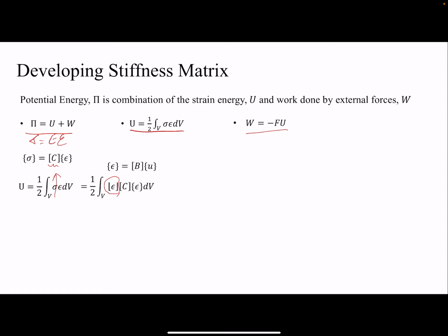So epsilon, I can simplify that. I found epsilon based on U, and I'm using the B matrix. So epsilon, I have 2 epsilon here. One is a column matrix. This is a column matrix. That's the value that I have. And this one is a row matrix. So it's just the transpose of that. And then we talked about that if you want to transpose a multiplication, you have to change the order as well. So I replace the value of epsilon, which I find based on U.